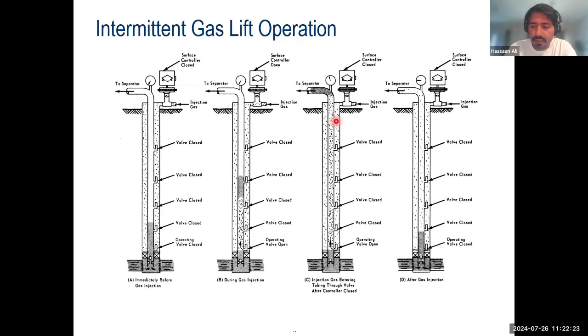So if I understand correctly, you are trying to understand what is the future of this technology going forward? Right now there are a lot of things happening, especially related to gas lift. There are different types of smart systems coming in. As I mentioned earlier, we have to change the valve whenever we have to change the venturi size or the orifice size. Now there are projects where we are developing valves with a smart venturi. That means it will change its diameter when it gets a signal from the surface, so there would be no need for an intervention. Smart gas lift systems are a topic of talk these days.